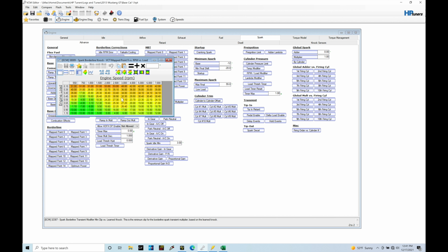We'll find that the volumetric efficiency, or the breathing of the engine, is going to be different. And therefore, because the cylinder filling is different and the cylinder pressure is different, we're going to have different amounts of spark timing demands when it's operating at a particular cam angle movement. And we have both intake and exhaust variable cam movement. So we'll find that these map points are associated to a certain pairing of movement in the intake and exhaust camshafts. As we'll jump back into our variable cam here in just a minute, we'll see what that means exactly, but just note that we have these map points.